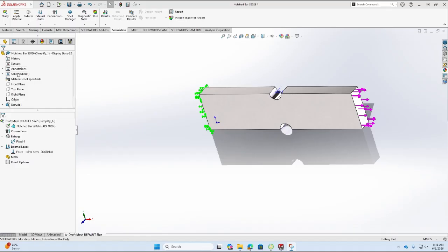The basic model setup has been completed. Now the main thing is to mesh it, right? And remember, I explained to you what meshing means. Meshing means dividing it or discretizing it into smaller units in which you can assume a certain functional distribution of your field variable. In this case, our field variable is basically the strain, right? And the strain field variable is linked to stress, and it's also linked on one side to displacement and on the other side through stress to the force. And that will allow the system to solve for it.